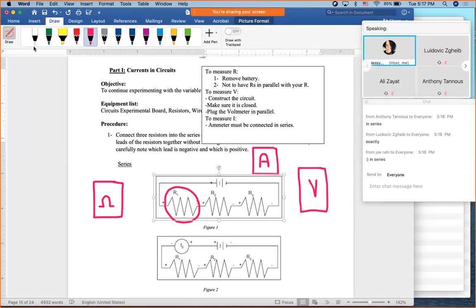So open the circuit like this. Let's say this is the resistor. You put the resistor like that, and you make sure the leg of the resistor is no more here, it's outside. And then you take your ammeter and you plug it in series with the leg that is up and where it was. This is how we do series connections, because you cannot construct the circuit in series. You have to open the circuit or lift one leg of the resistor and measure between where it is and where it was.